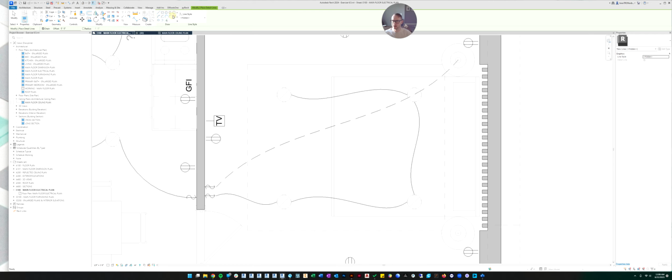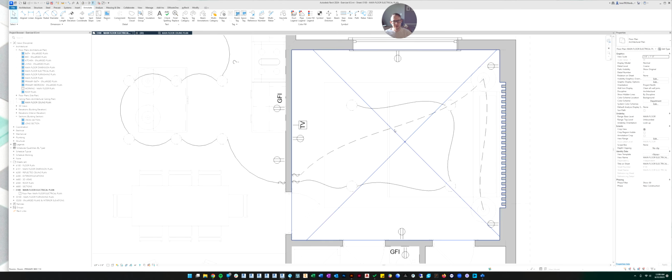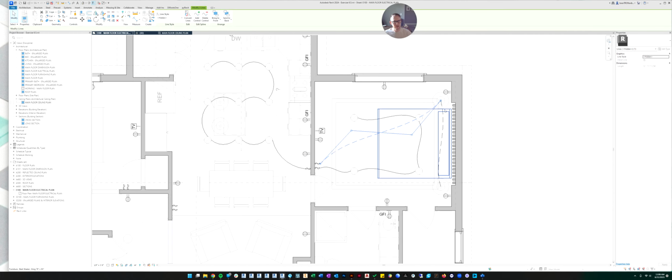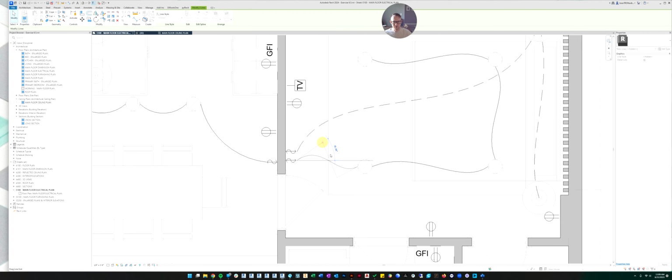So we'll do the same thing to connect these two. Oh, whoops, I need to go back to the spline command. And I'll do snap center, SC. And here we go. And then snap center again, SC, click, and hit enter to stop my spline. And now you can see there's this curved line. And if I don't like that it's running through my other light, which I don't, you can pull these little points and you can change the way your wire looks. So you can do that to any of them if you want it to be more exaggerated. You can come back in here and adjust your lines like that.